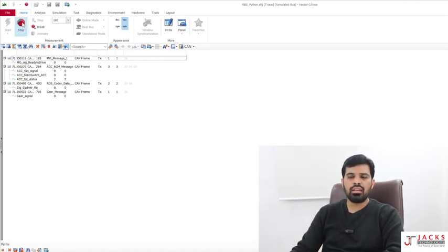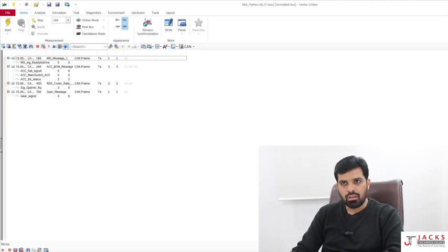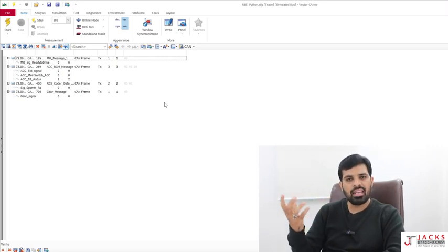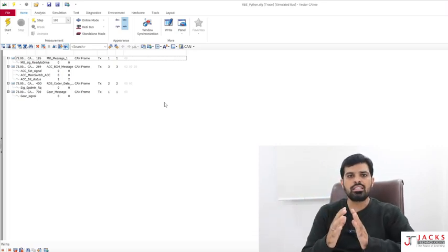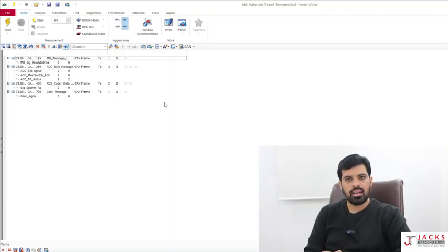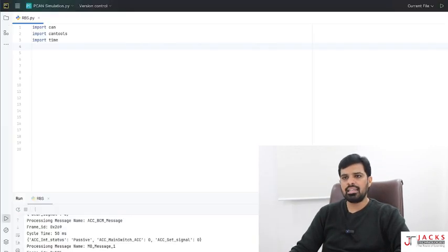Now guys, we need to create the rest bus simulation using Python. For which interface do we have to create it? We need to create the rest bus simulation for the PCAN interface. As I am using the PCAN hardware, I need to create the rest bus simulation for PCAN. So whenever I want to automate any test cases through PCAN, the rest bus simulation is needed so that through other files I can dynamically update the values, right? Now I'll explain how to create the rest bus simulation with Python. Let's get started.